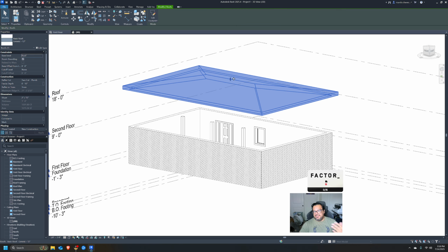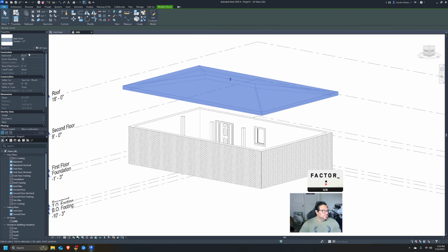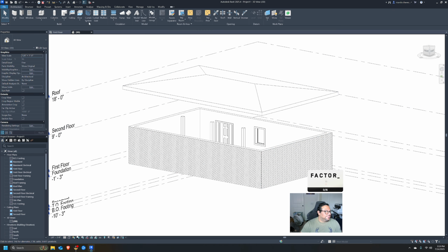And you can type in whatever, 1 feet, 2 feet, and it'll do it. It knows that it's going to be over 12. So we do 4, it'll be 4 over 12. We do 9. So there, it updates automatically. So for this, we'll do 2 just to make sure. And there. So that's how we got our roof, right?